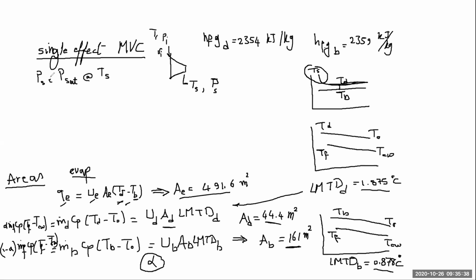We know the value of TS, it is given to us. So go to the thermodynamic tables or go to the EES or any property calculator to get the corresponding pressure. And the same thing for the outlet of the compressor. For the inlet of the compressor, the P inlet is basically the saturation pressure at TV or at TD, both are the same.